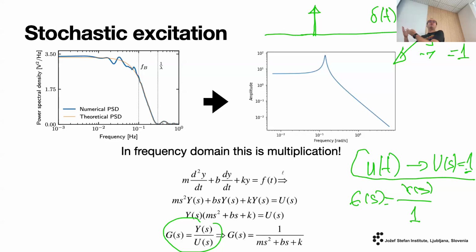The idea is, can we do the same with electrochemical systems? Can we ping it and it will ring down its guts? Okay, we cannot do it electrically this correctly, but we can do it in a stochastic manner. So can we generate a random signal that has a flat spectrum? Let's do this.